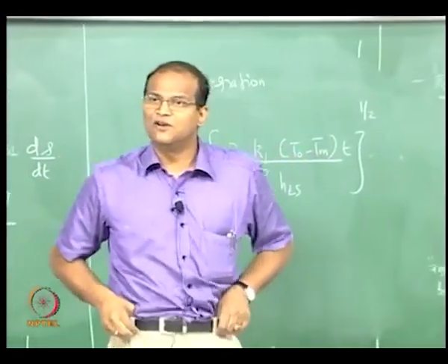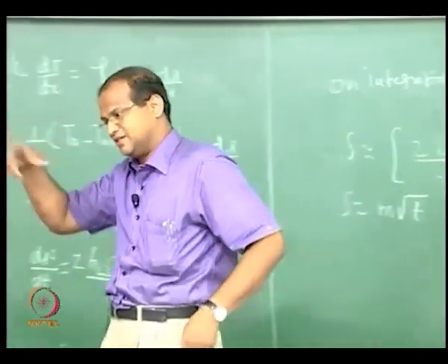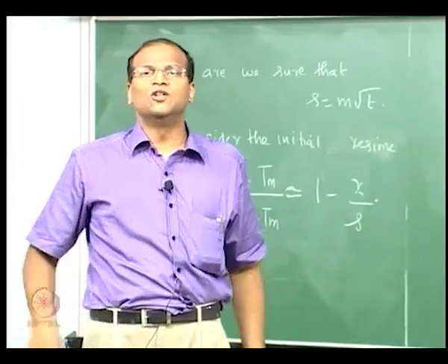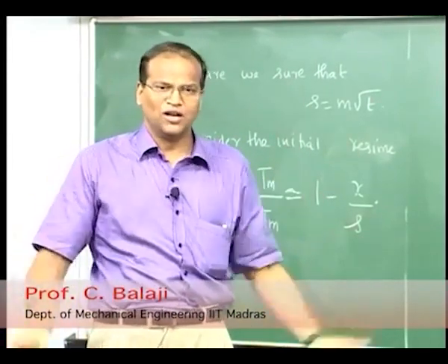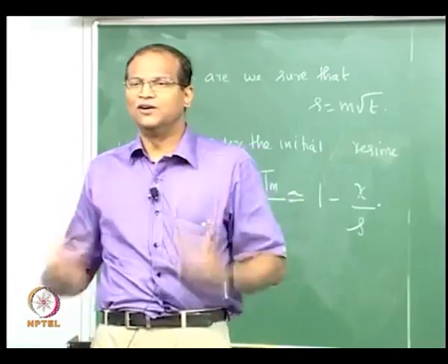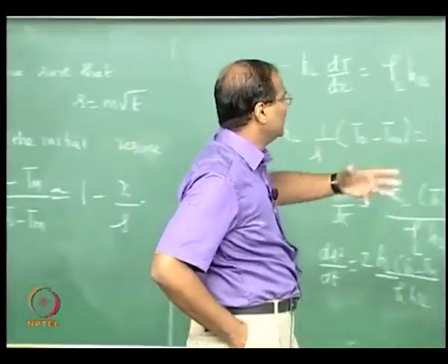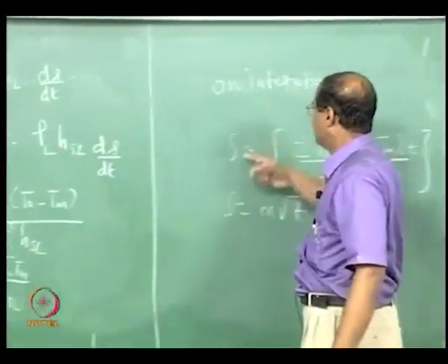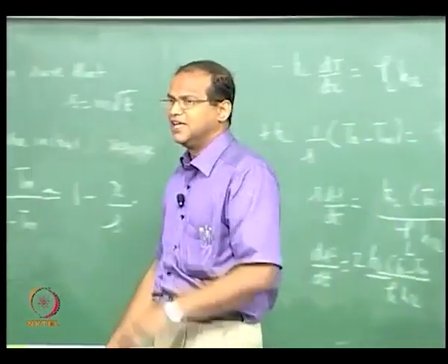So S will be a function of x and y apart from time. S itself is a function of time, that is one thing, and the melt front will also be two dimensional. So once you want to model those cases, you want to consider subcooling, superheating, you want to consider mushy zone and all that, the analytical solutions will break down. You have to take recourse to numerical methods. You can write your code, and the most important thing is the capturing of this melt front. That is why we spent considerable effort now to get S. Capturing this melt front as a function of time is a key engineering result.